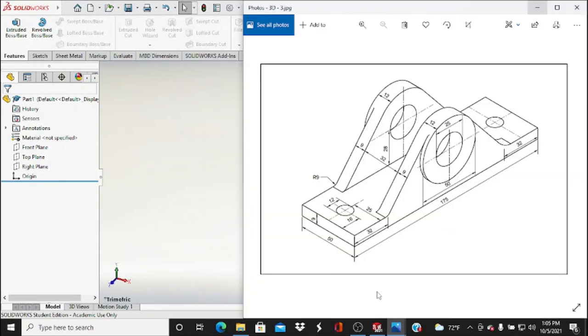So our first one we're going to do is this swivel base. For this one we're going to use the mirror feature, and basically just a simple approach at the bottom. You have to visualize your part, what it looks like. So right now at the bottom, we're just going to do a rectangular shape. We know it's going to be in millimeters. That's our units. We have a few fillets, so I think we can fix that once we make a triangle from here, just straight ahead. That will fill it right away. And then that's it. So I think we're going to do mirror features too as well.